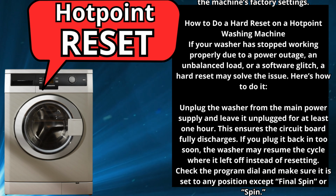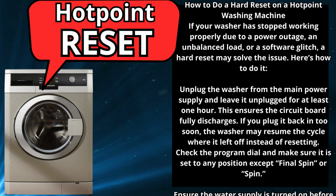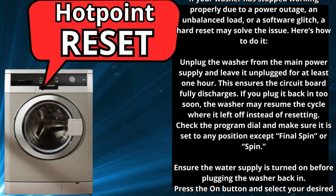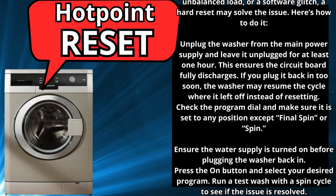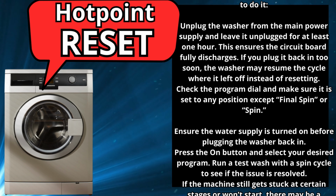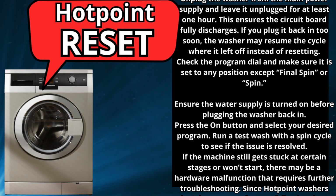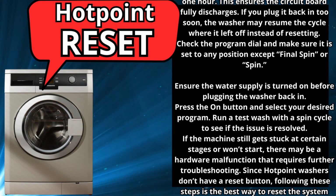Unplug the washer from the main power supply and leave it unplugged for at least 1 hour. This ensures the circuit board fully discharges. If you plug it back in too soon, the washer may resume the cycle where it left off instead of resetting. Check the program dial and make sure it is set to any position except final spin or spin. Ensure the water supply is turned on before plugging the washer back in. Press the on button and select your desired program. Run a test wash with a spin cycle to see if the issue is resolved.